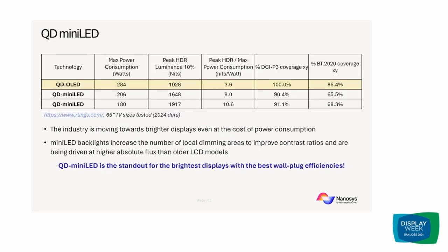Some of the products that you'll see now with QDEF have to do with QD Mini LED. QD Mini LED is one of the newer display technologies that's out there. Compared to traditional LCD TVs, Mini LED backlights increase the number of backlights that are there. It increases the number of local dimming zones, the contrast ratios improve in the display, and the absolute brightness can also be higher.